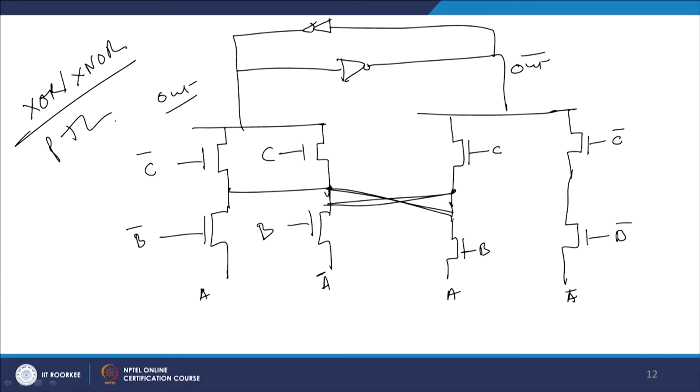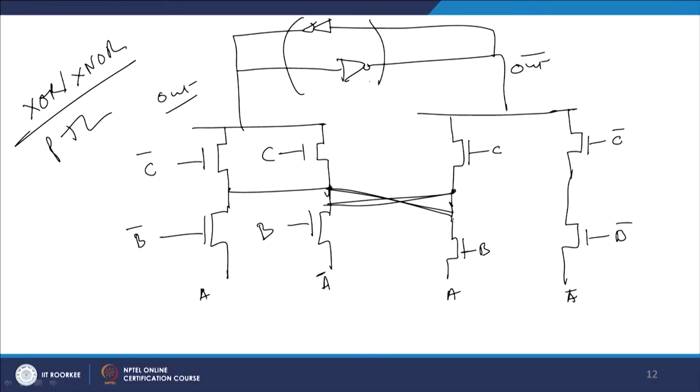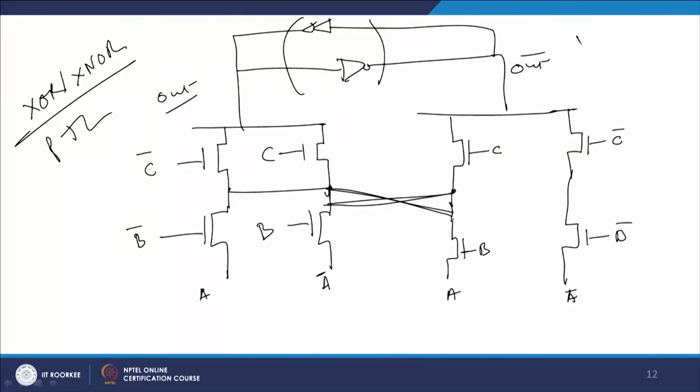PTL logic. So, this is basically your swing restorer PTL logic. Why is it a swing restorer? Because these two latches here try to restore the swing to VDD and ground. So, for any pass transistor logic lowering the swing, this pull up inverter pair will pull it up to a much higher value and try to latch it to that higher value available to you. The only problem which people face in pass transistor logic, as I discussed earlier, was